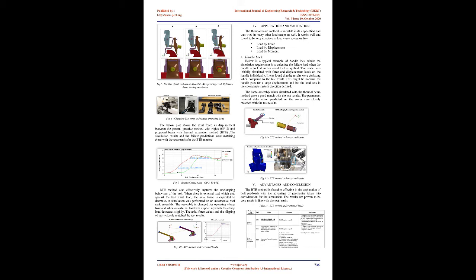6. Create a cylindrical joint between the bolt and nut, which makes sure that both the components are always in line even if there is a relative movement during the analysis.